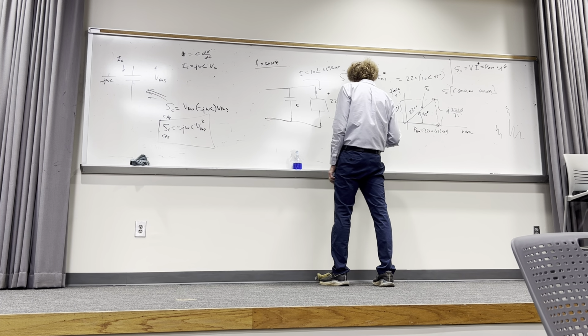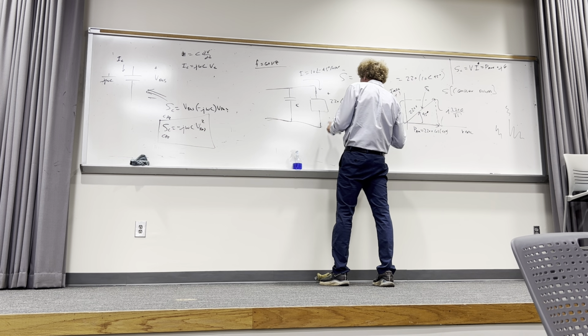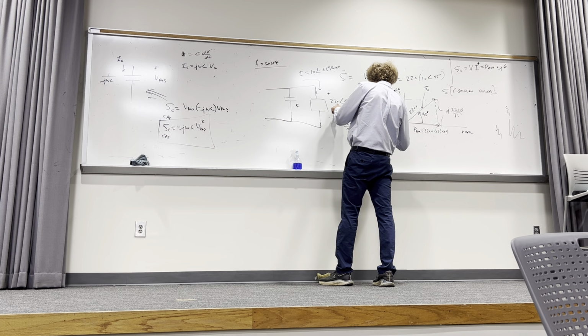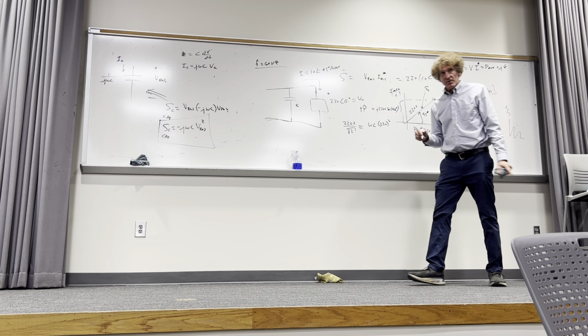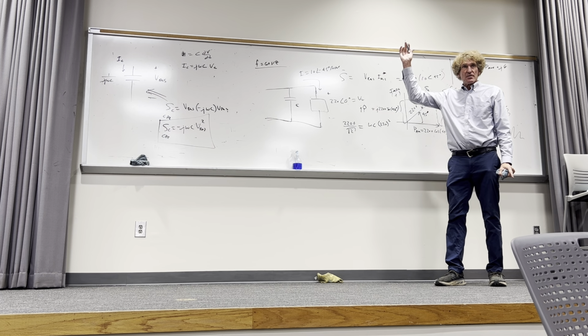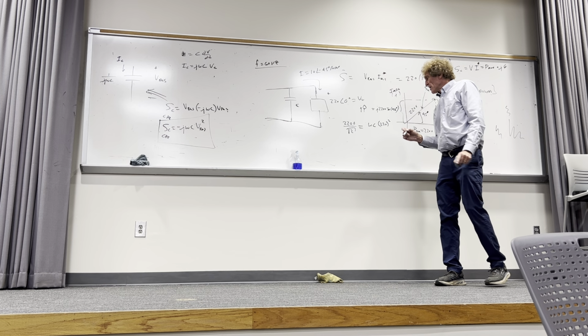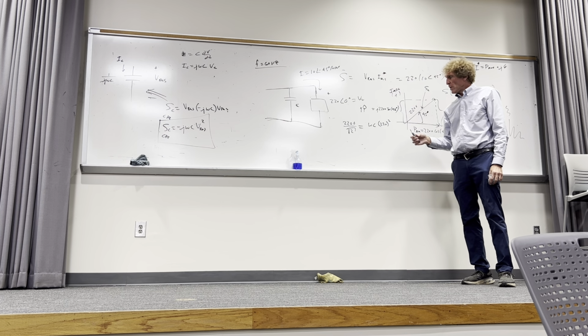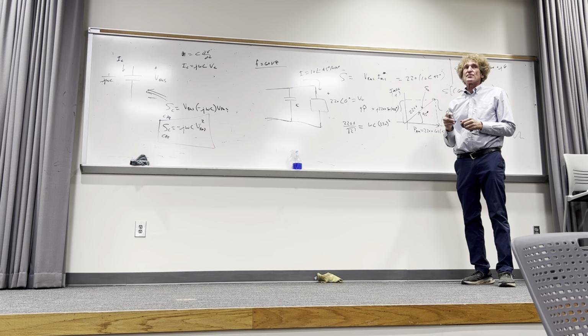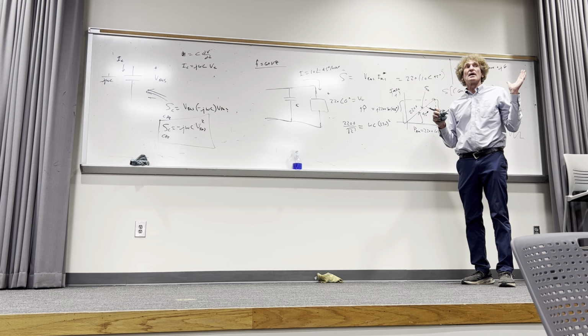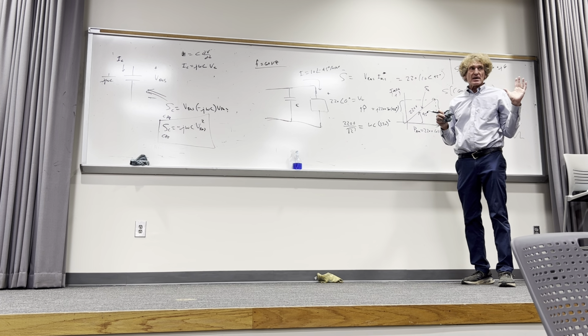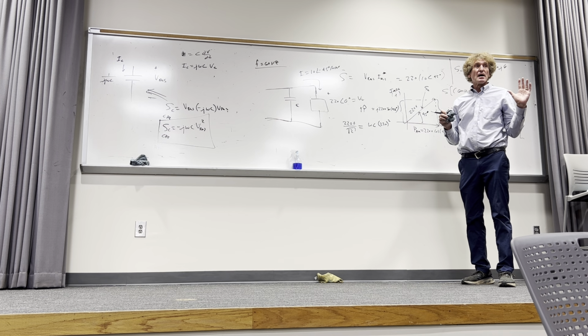And then I take omega C times VRMS squared. Well, the voltage is 220 RMS. You all see what I'm doing here? Now, a question to people: we're solving for the capacitor, but what is omega? 377.